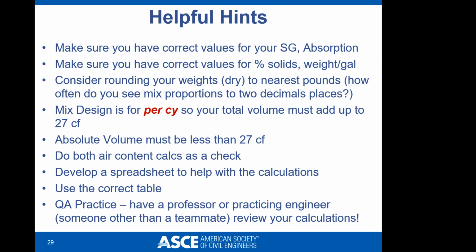Years ago, I was looking at a team and looked over their calculations. They were using a weight which they thought was per gallon for a particular admixture. They basically said, hey, we weighed the jug, and this was the weight, so therefore they had a weight per gallon. I took a look at the container, and the container was more than a gallon. It was like 1.3 gallons, so the weight per gallon should have been different. And it was an honest mistake. They assumed it came in a gallon jug, and it wasn't a gallon jug.